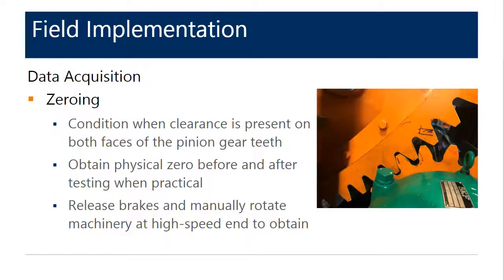So with the hardware connected to the data acquisition system, the strain gauges are ready to be referenced to a zero condition. Strain gauges are not absolute measurement devices. They require a reference point. Just as when using a scale to measure the weight of an object, the scale must be tared to the unloaded condition. The change relative to the zero reference point is the actual shear strain the shaft is subjected to and what is recorded. For many mechanical systems, obtaining a zero torque condition is relatively straightforward, simple, and safe.